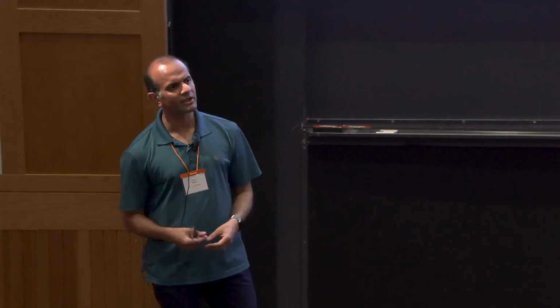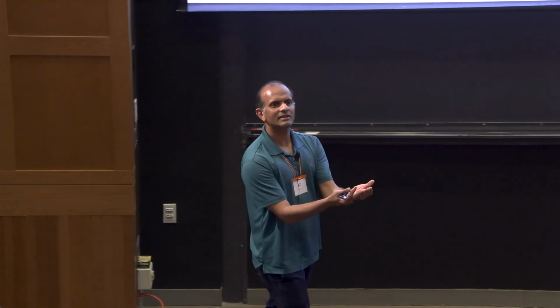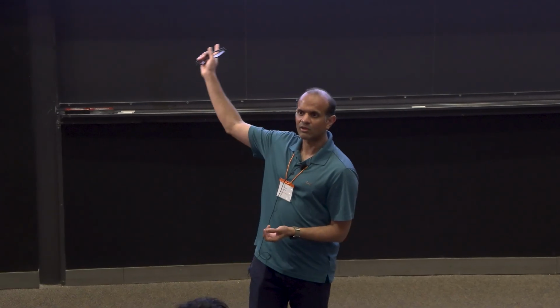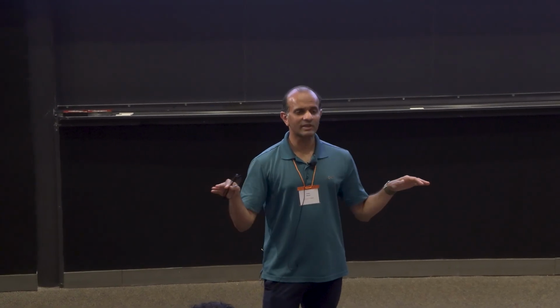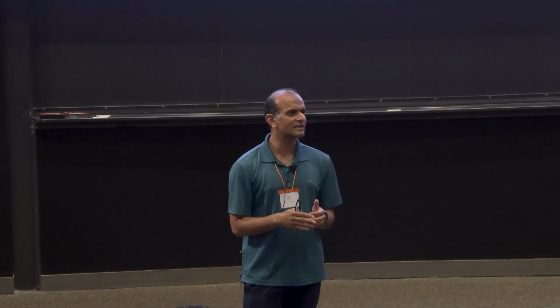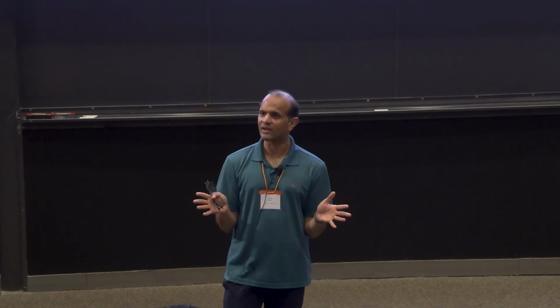At some point, they dissipate. How long can they stay as an eddy is determined by this Kolmogorov length scale. So on an average, eddies that are smaller than this eta will dissipate very fast, very quickly. So you don't have to really care about them.